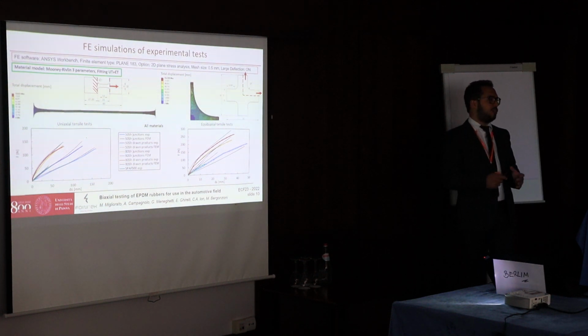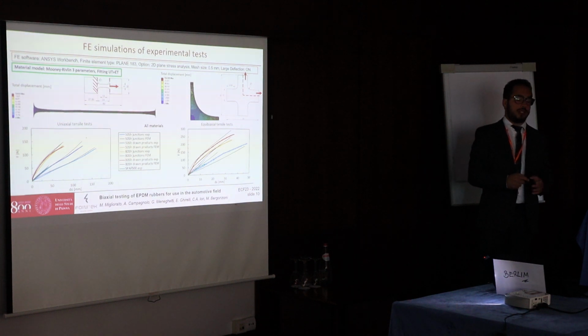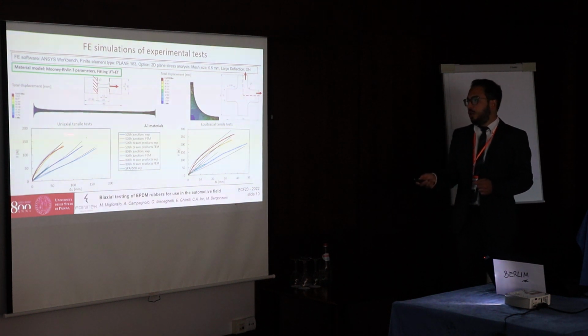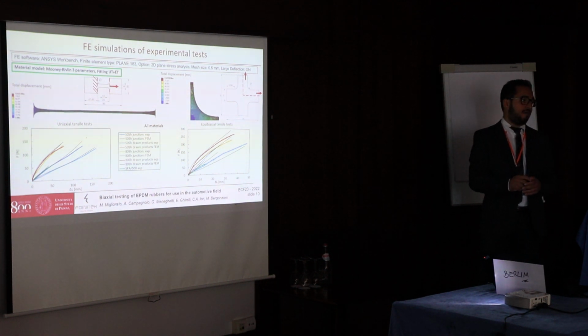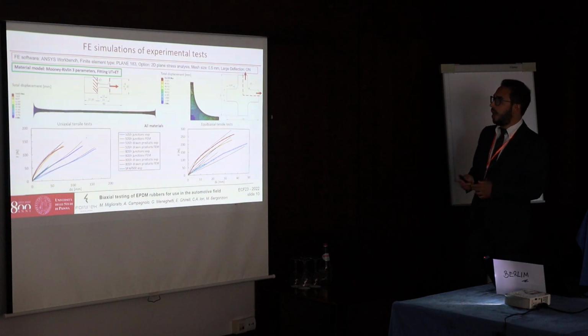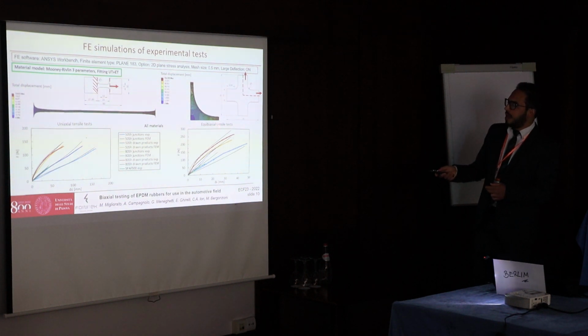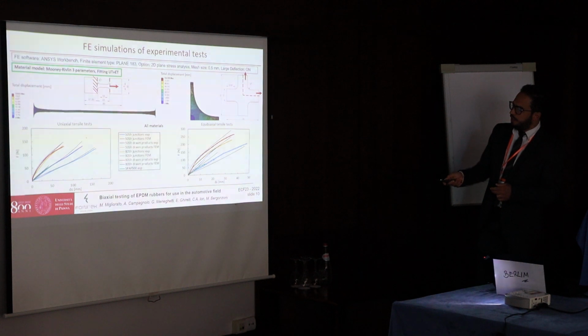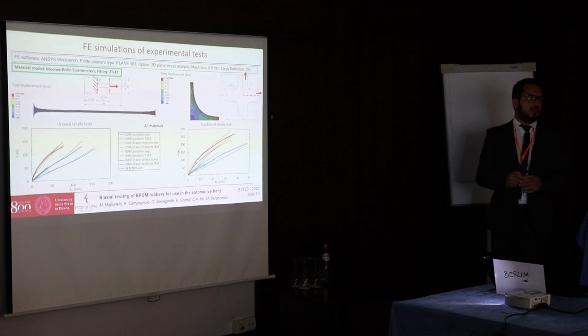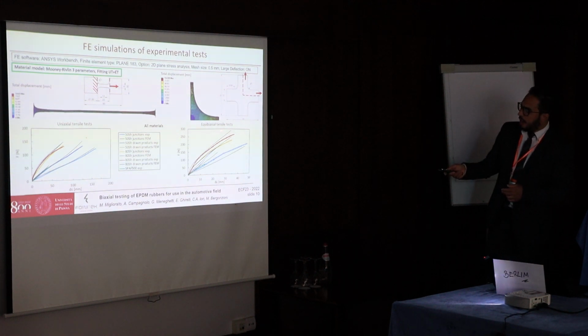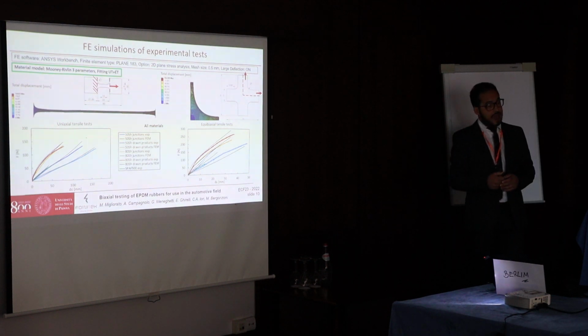We have compared such curves with the experimental ones. It can be observed that for the uniaxial tensile test, the agreement between simulated and experimental curves is very good. While under equibiaxial loading, the agreement is fairly good in the first region of the curve for a reduced strain value, while a general trend to deviate has been observed for large strain values.